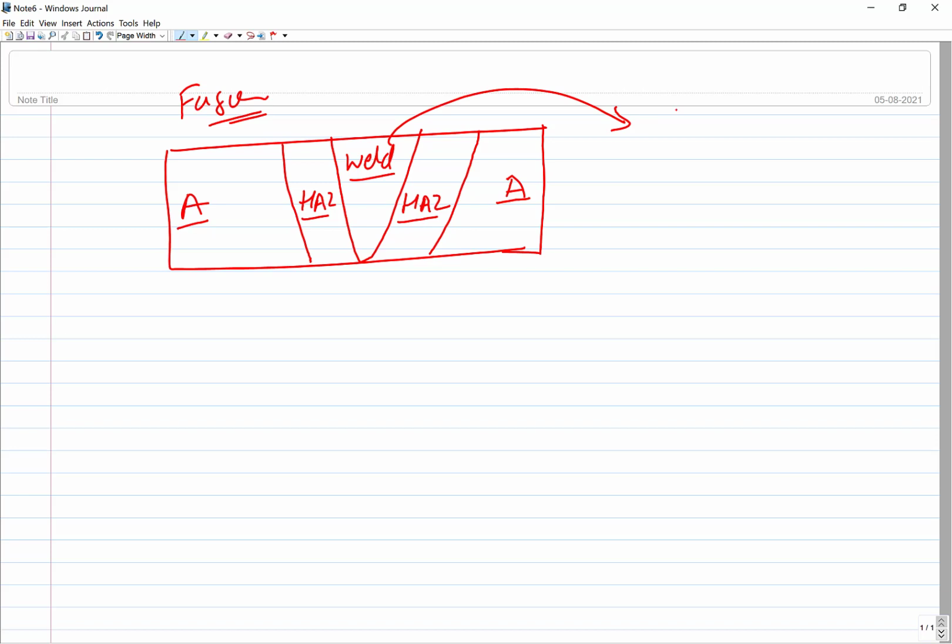there are two possibilities. One is there is a possibility to change the filler, which is where we use the filler metal. But in autogenous welding there is no choice. Do you know what autogenous welding is? The two edges of the plates are joined without the use of filler metal. Resistance welding is also an example of autogenous welding. Friction welding is also an example. Spot welding of thin sheet is usually performed in autogenous mode because we don't use any filler.